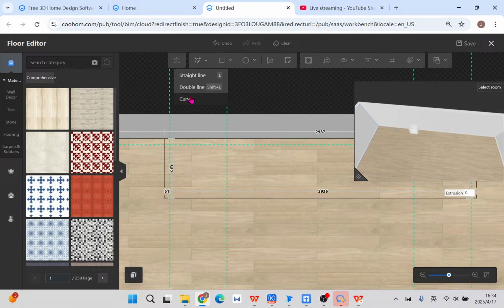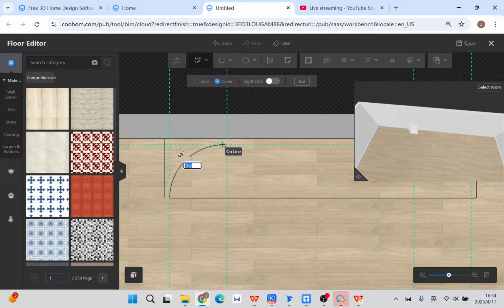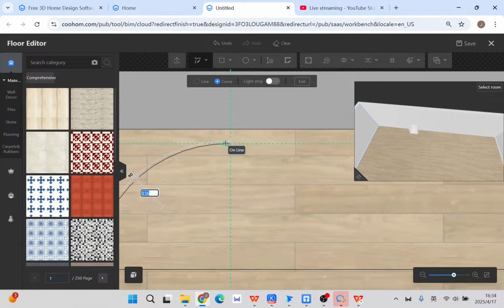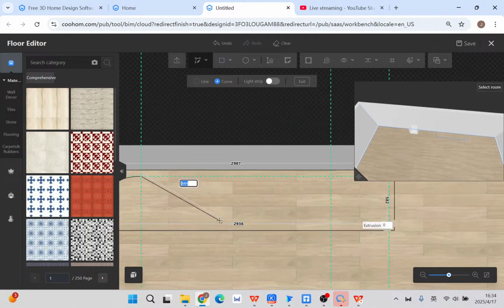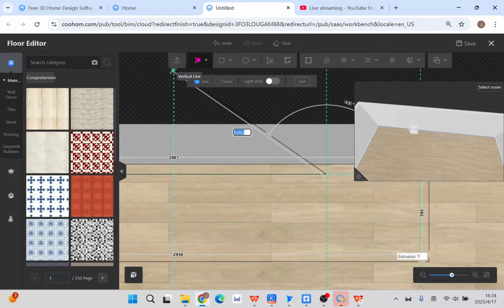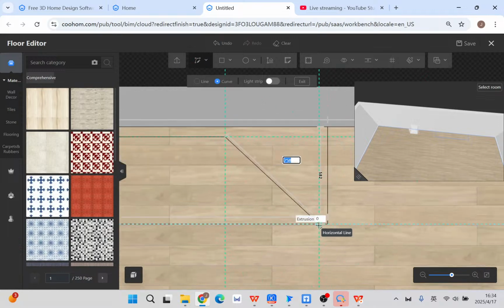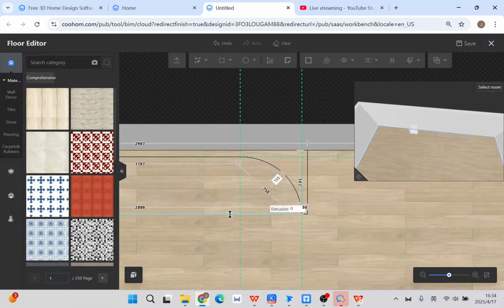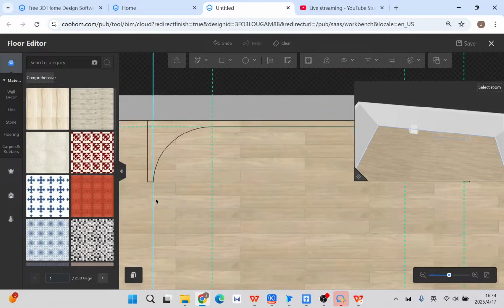And then curve line from dot to dot and just move left a tiny bit to change it. And of course, you can type in a number, for example, 155. Okay, make it proper. And now, continuing drawing, you can directly switch to the straight line. Now the lines are still connected. And here, change it again, back to curve, endpoint to endpoint, 155. Okay. Now we finish drawing, click this useless line and delete.